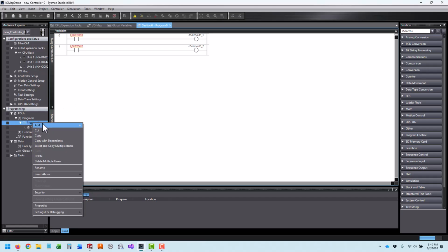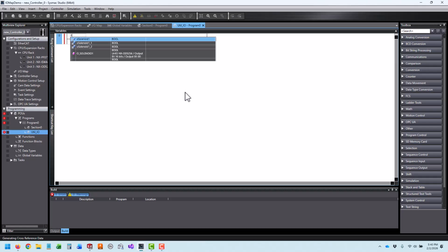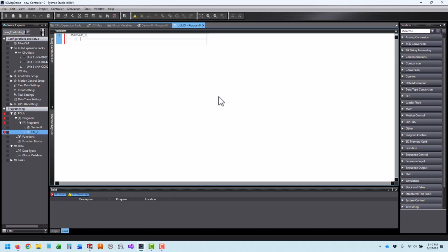And then I would create another section of your program and call it, usually I do util, like a utility for I/O. And here you would do either of your solenoids will turn on your actual solenoid. So if you call this from either spot in the program, maybe you have a setup over here, maybe you have the main program over here, they both can control the solenoid. This is how you do the output.